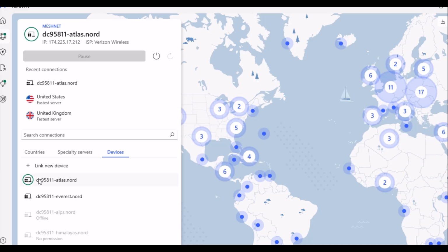So that's why I had to go with a completely different route for my receive audio, because by nature the receive audio is just quiet for long stretches of time, and then all of a sudden, out of nowhere, it starts sending audio. So you've got to have something that's ready for that at any time, and then you can just start spraying out the UDP packets as they come in.